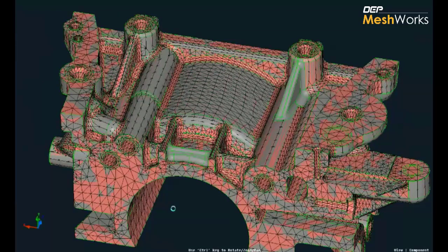And once these changes have been updated, the user can give a mesh template, and internally what happens is only those local regions are meshed with a mesh template. It need not be the same template, it can also be a different template, and it also makes sure that the mesh is all stitched and the dependencies are updated. And dependencies meaning the element sets, node sets, surfaces, etc.